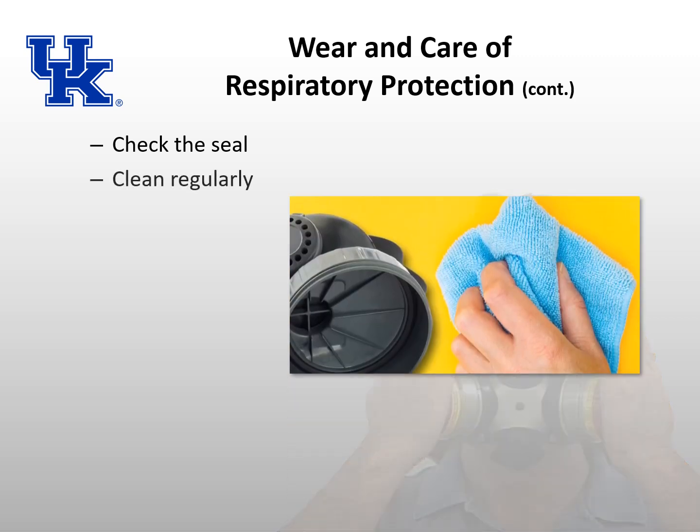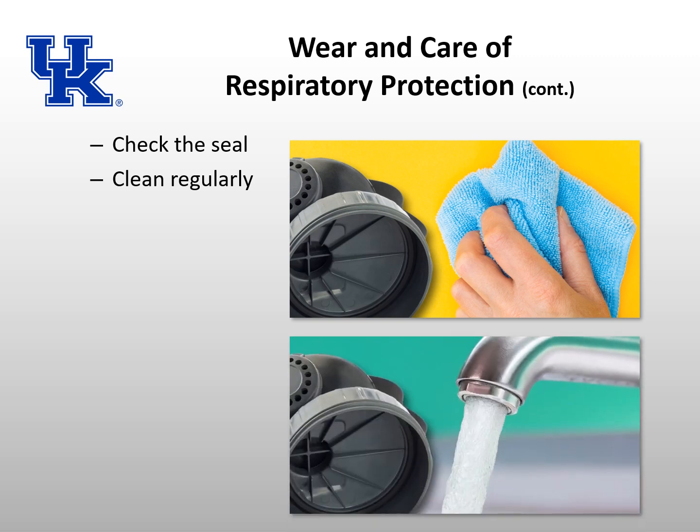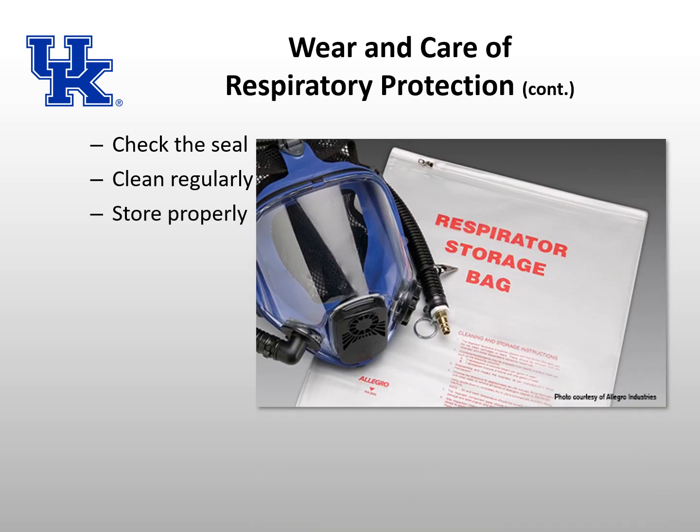You should clean your respirator regularly. Daily cleaning might involve using an alcohol wipe. A thorough cleaning needed periodically involves taking the respirator apart and cleaning it with soap and water, then leaving the parts to air dry. It is also important to properly store your respirator in a sealed plastic bag and store it so the natural shape is not distorted.